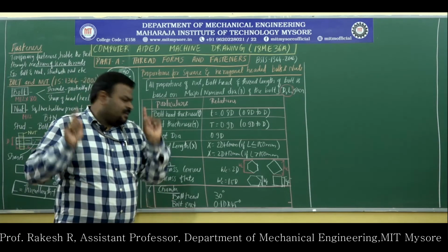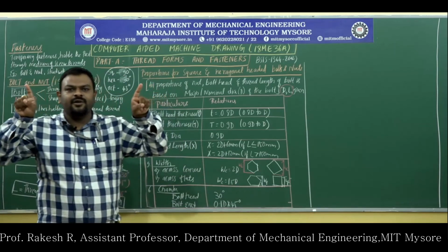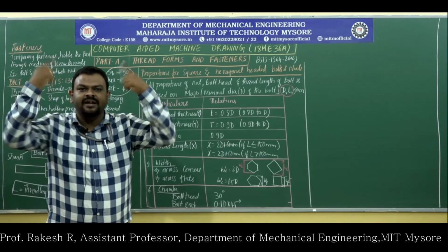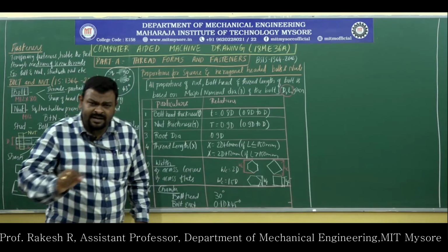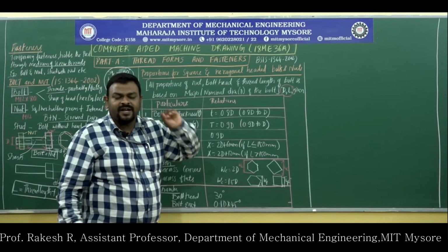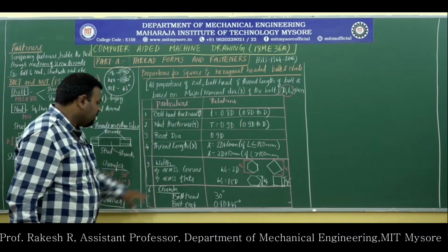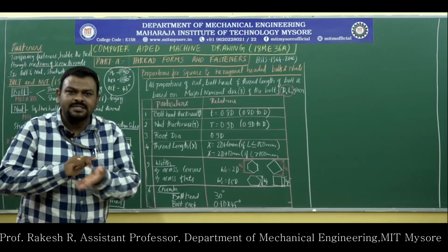Got it? If the bolt diameter is D, then the corner to corner distance of the hexagon should be 2D. That is very important. Whenever we take assembly drawings, this point is 100% essential. Very important. Then the chamfer. What is a chamfer? We need to have smooth edges.